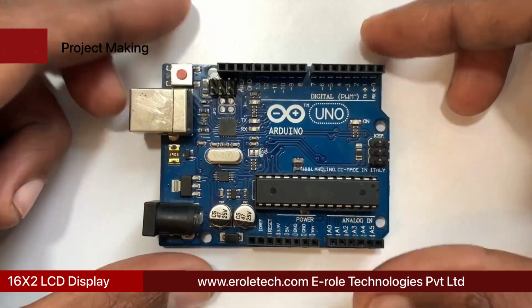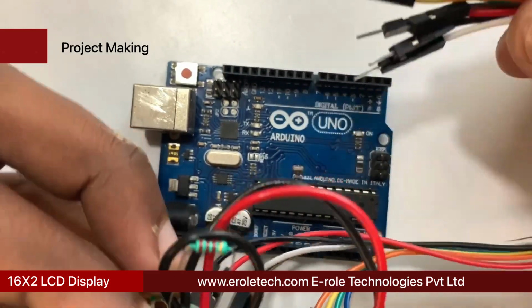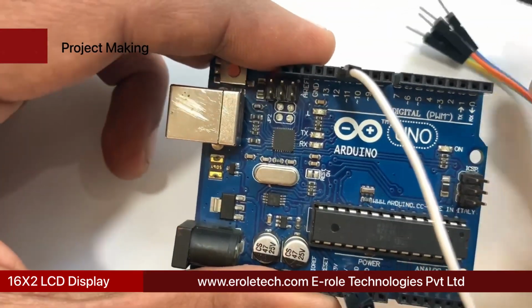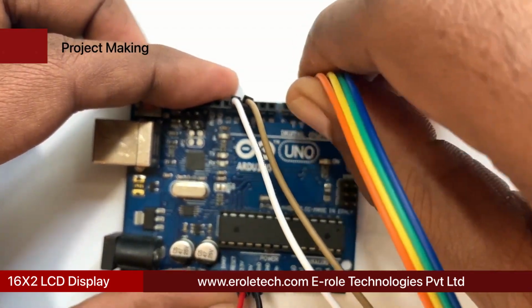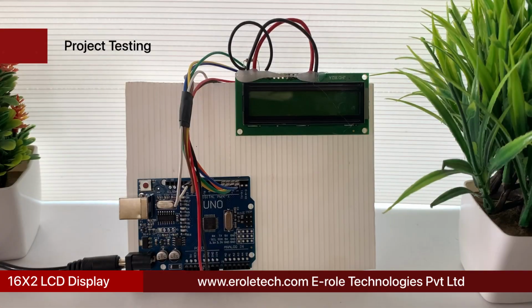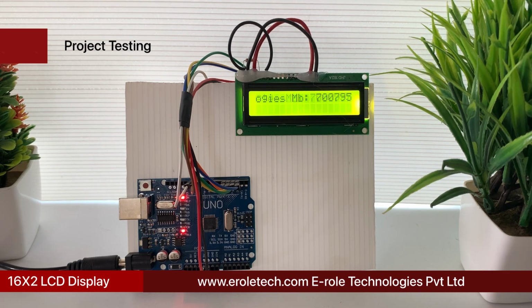Now we will connect the LCD display with our Arduino hardware board. Connect the red wire with the 5-volt pin and black wire with the ground pin. Now connect white, brown, orange, yellow, green, and blue wires with pin number 12, 11, 5, 4, 3, and 2 of Arduino respectively. Now we will power up our circuit and test its functionality. We can see that the message is scrolling on the LCD display, as we have declared inside the program.